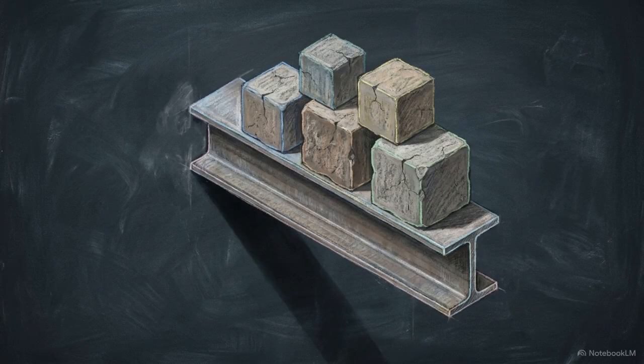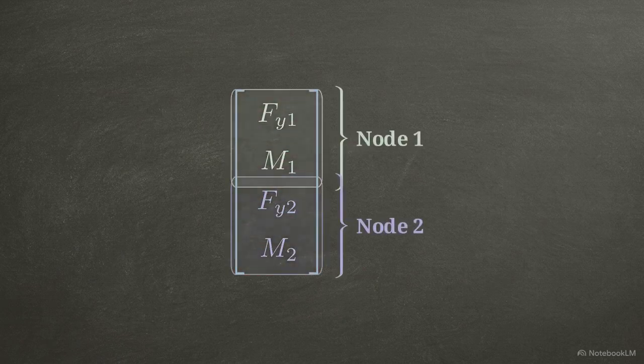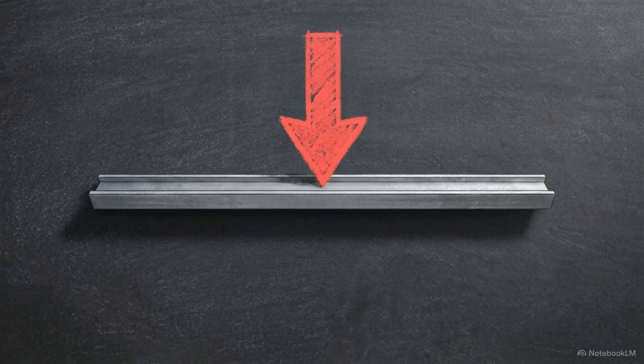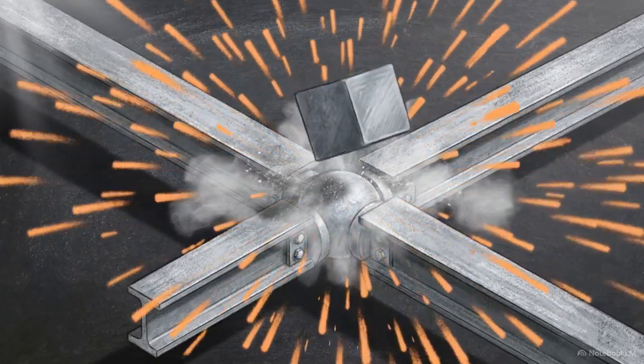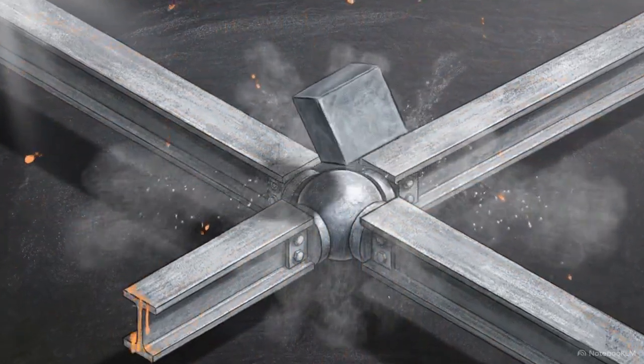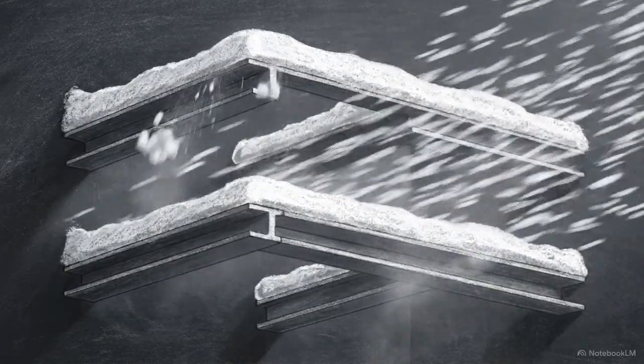With the geometry established, we can look at the external forces acting on the element. In our system equation, these forces are represented by the loading vector. This vector must account for all external loads, but it can only accept data at the specific node locations we've defined. The simplest forces to account for are concentrated loads. When a force strikes exactly at a node, we can plug its value directly into the corresponding slot in the vector. However, most real-world forces, like wind or snow, are distributed.